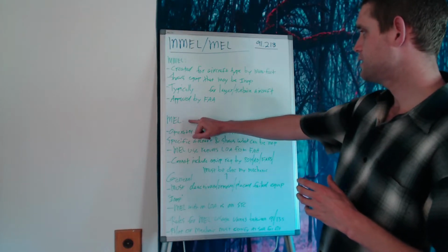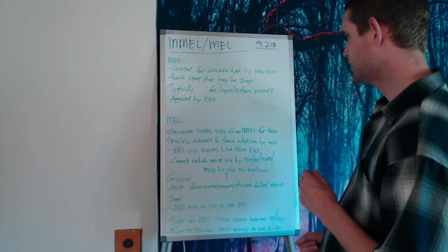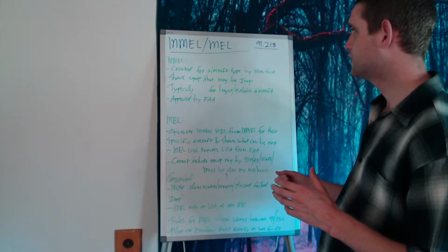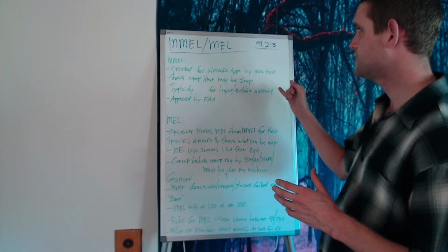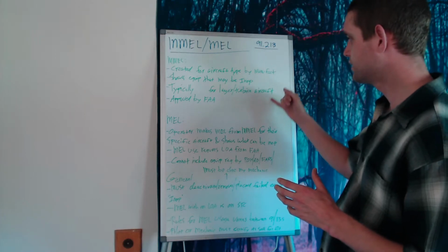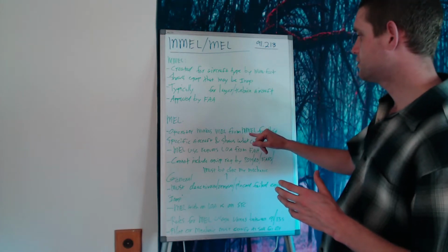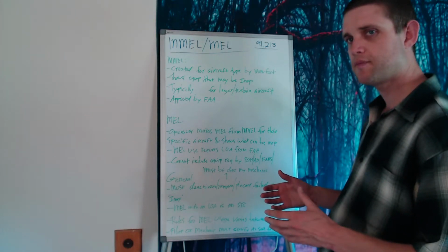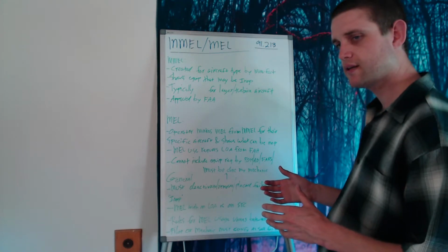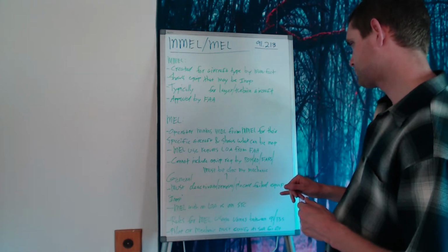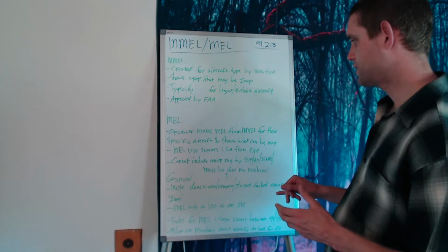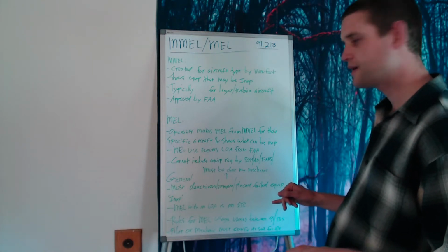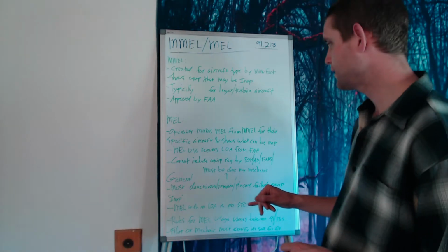So next we have the MEL, or minimum equipment list. The operator or the owner of the aircraft will obtain the MMEL, the master minimum equipment list, and then create the MEL using that list, and modify it for the installed equipment and the particular operation that the owner wants to do with that aircraft. So the MEL shows what kind of equipment can be inoperative and still have the aircraft safe and legal for flight.